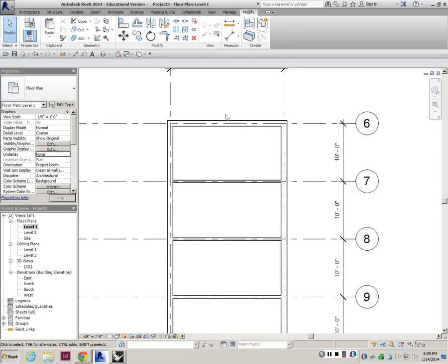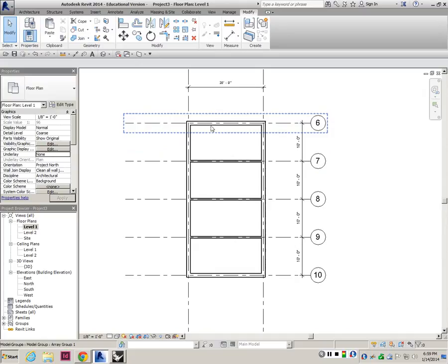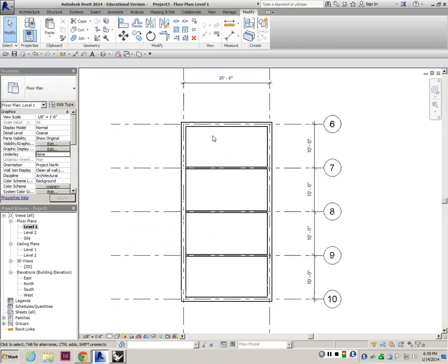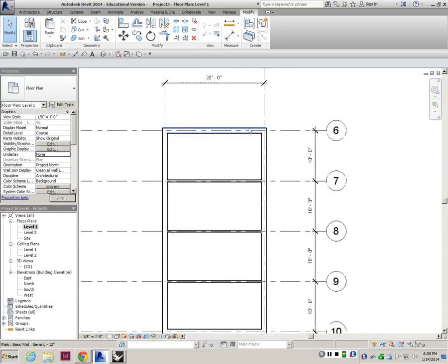So what I'm going to do is draw an internal furnishing to one of them and then create a group and make copies of the group to the other ones. And then you will see how groups could work and how important they are in Revit to replicate similar detailing.